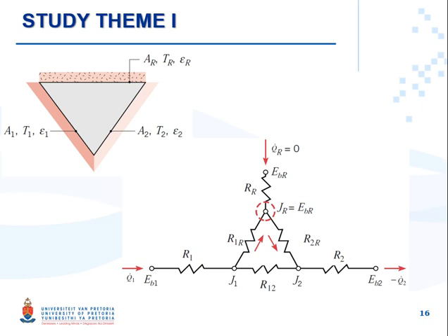For example, it is acceptable for real surfaces that are well insulated on one side and have negligible convection effects on the opposite side. In this case, we are assuming that surface R in this picture is well insulated and convection effects are negligible.